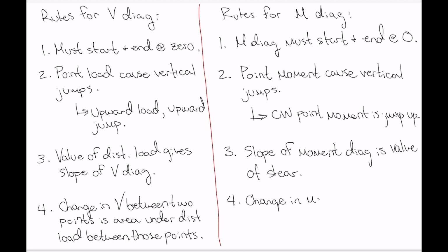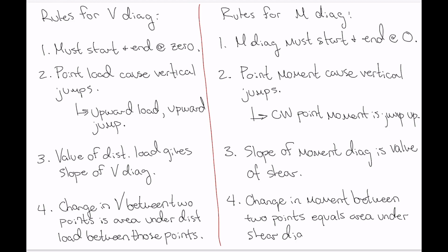Change in moment between 2 points equals area under shear diagram. Okay. So 4 rules for drawing the shear diagram and 4 rules for drawing the moment diagram.